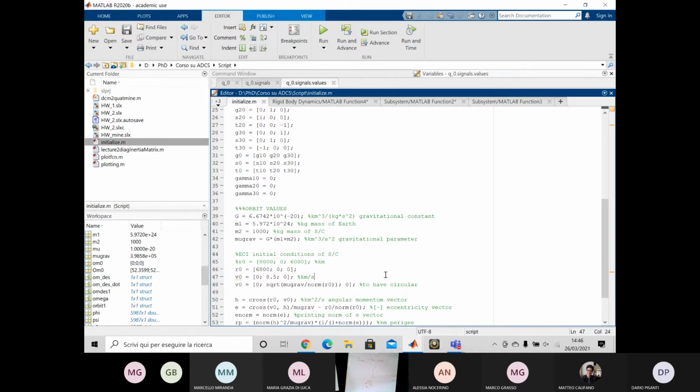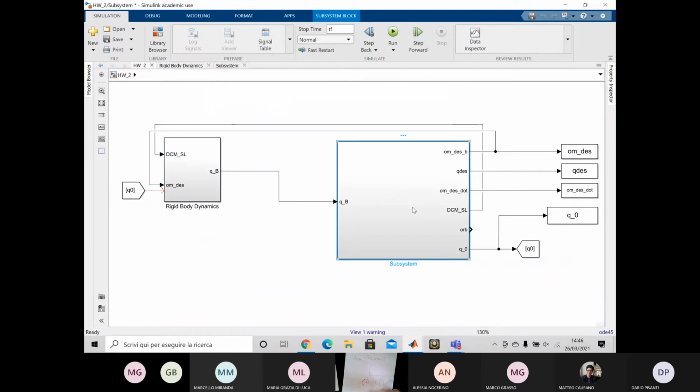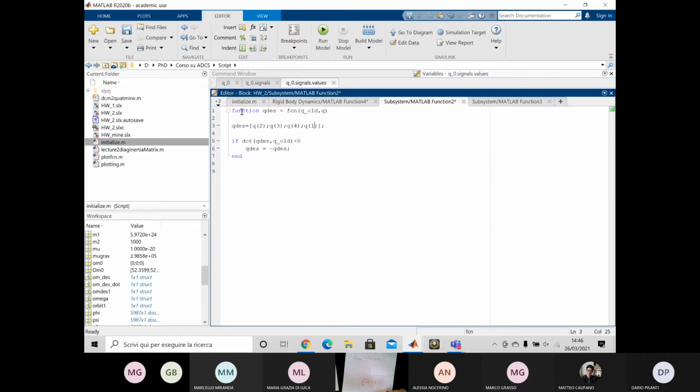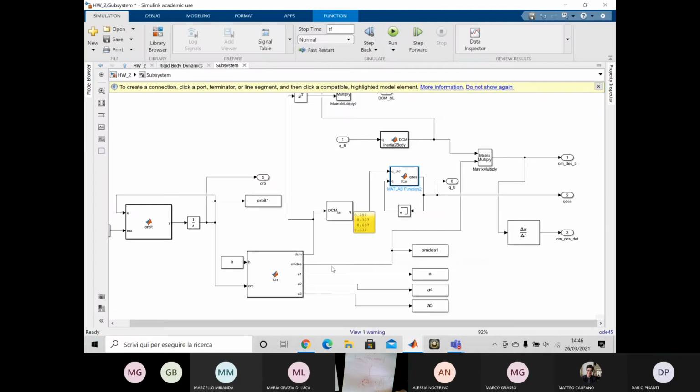So you want your spacecraft to be oriented this way, and you're telling me that the initial quaternion corresponding to this is 0, 0, 1, 0? Yes. The last is the scalar one, and how did we define this? Cosine theta over 2? Correct? Yes, that's our definition of quaternion. I think so. And so being 0 means that theta is pi over 2. Correct?